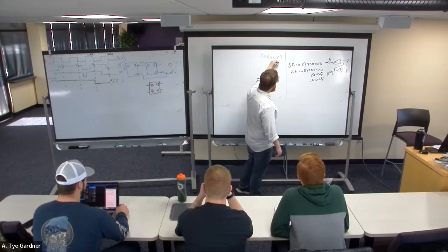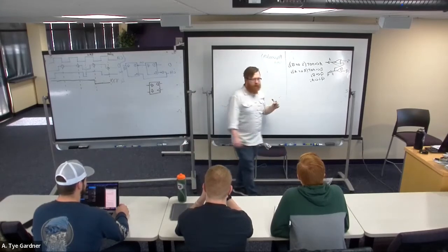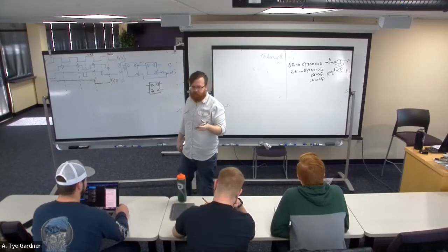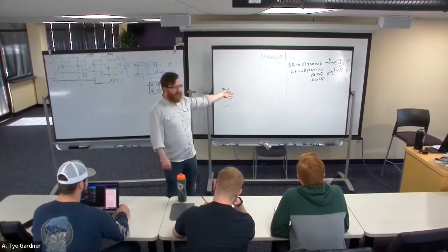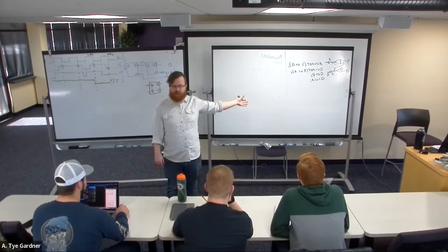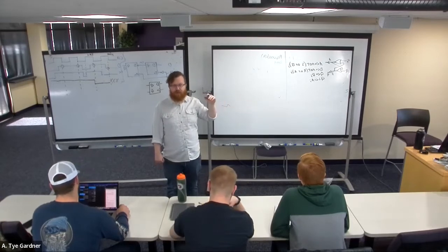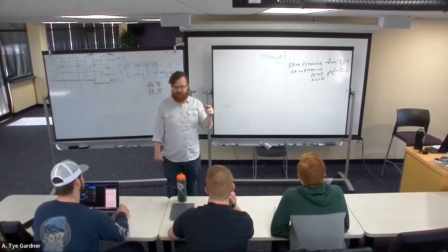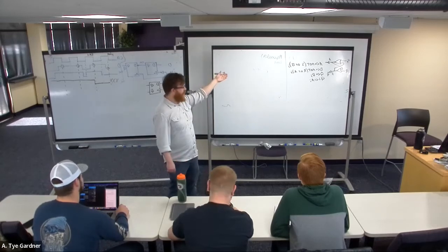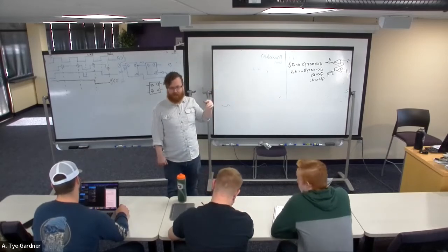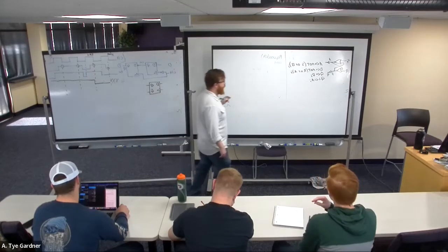It needs to begin. Again, if I was writing this in VHDL, I would write end process immediately because we know there's going to be an end process here. And if you forget them, the errors are terrible to hunt down. So if you ever write process begin, write end process and go back and fill in the remaining code. That's a nice helpful tip.